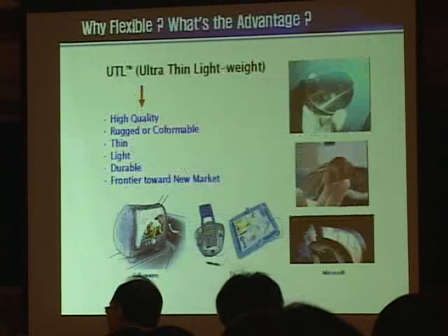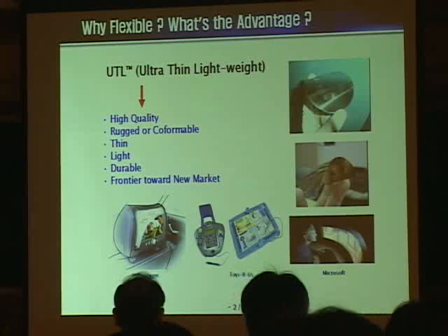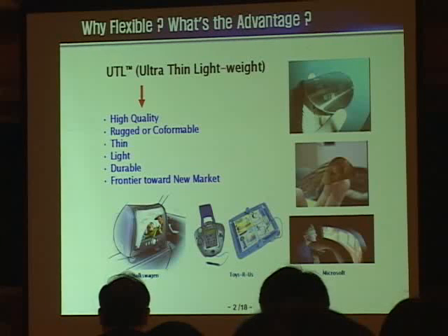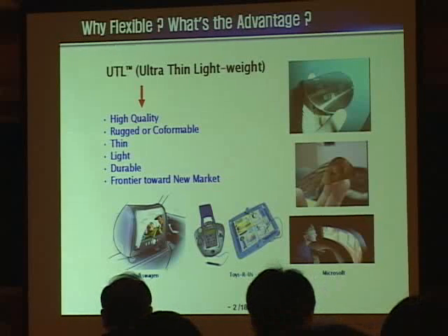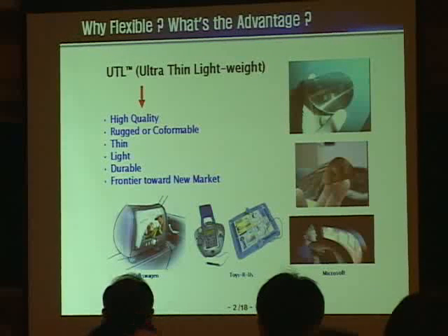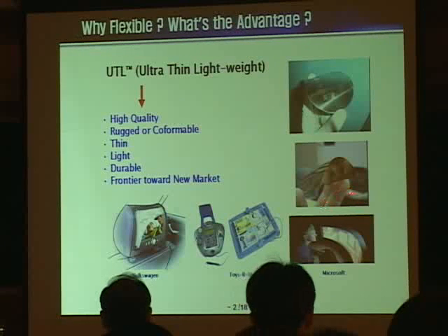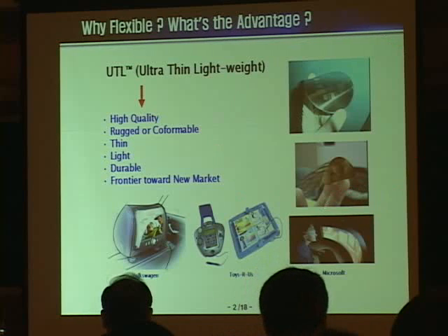Next slide, please. There are two big trends in flexible display fabrication. The first will be high-performance display fabrication by using existing TFT technology such as LTPS or amorphous silicon TFT. Especially in this approach, many people are using metal foil as a substrate, because the thermal stability of metal foil is best for the flexible substrate.